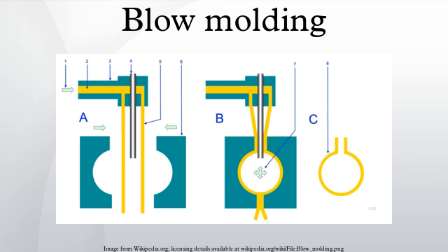Continuous and intermittent are two variations of extrusion blow molding. In continuous extrusion blow molding, the parison is extruded continuously and the individual parts are cut off by a suitable knife. In intermittent blow molding there are two processes. Straight intermittent is similar to injection molding, whereby the screw turns, then stops and pushes the melt out. With the accumulator method, an accumulator gathers melted plastic, and when the previous mold has cooled and enough plastic has accumulated, a rod pushes the melted plastic and forms the parison. In this case the screw may turn continuously or intermittently.